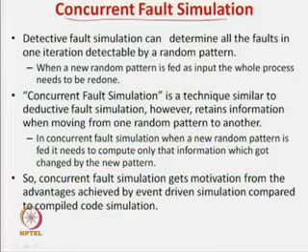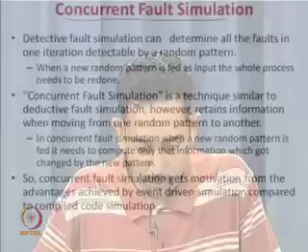The last fault simulation technique we will study today is the concurrent fault simulation. That is actually the same thing as deductive fault simulation, in that in one scan of the circuit you find out what faults will be detectable, but at the same time we are not going to throw away the results. If by applying one pattern we find out that these faults are detectable, we do not eliminate all the results. We apply another pattern and try to recompute only those things which are getting changed, that is event driven simulation. So you can think that concurrent fault simulation is event driven simulation plus deductive fault simulation. That idea you have to feel.